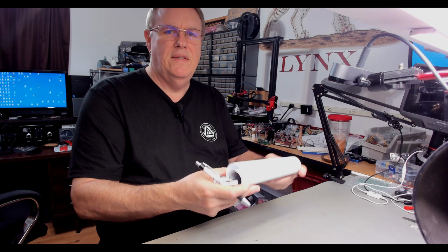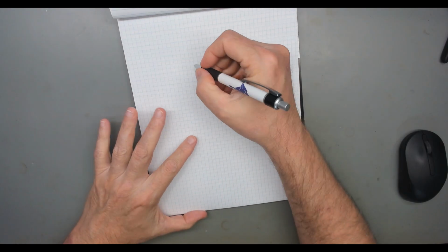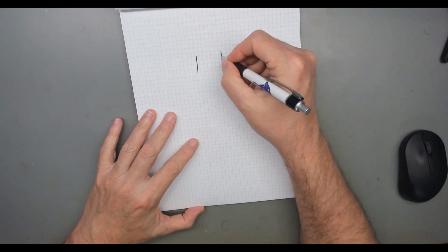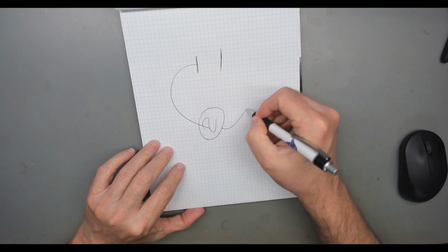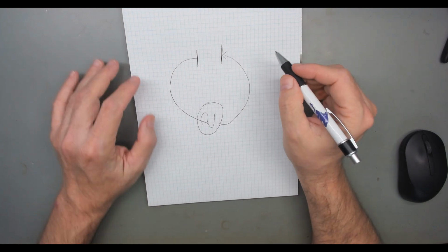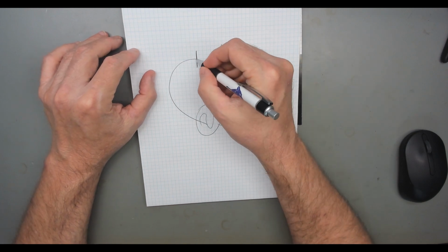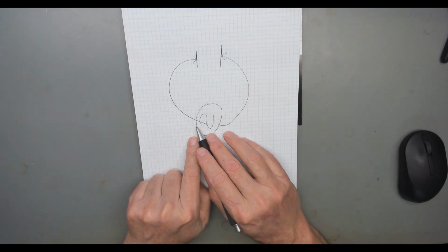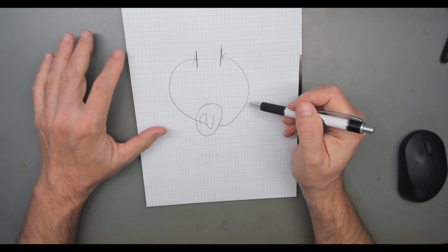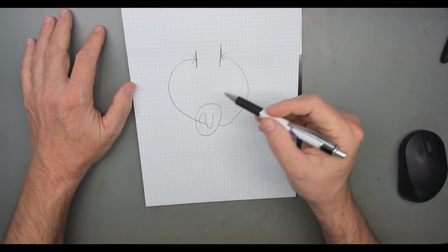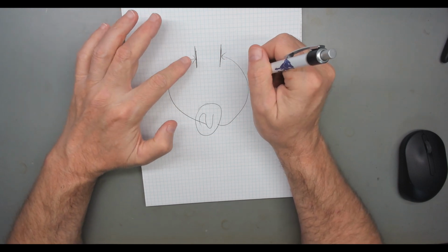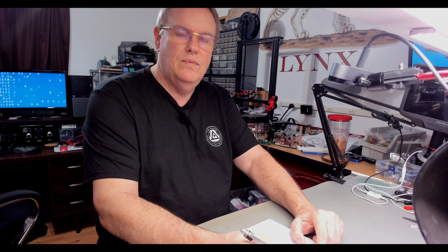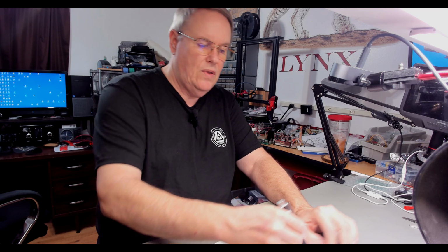Let's think of it from an AC point of view. AC is going to do the same thing. Here's our plates. We're going to put an AC source on the plate. What's going to happen is, depending on which side we are on the AC cycle, electrons are either going to be moving in this plate or moving out of this plate. It's going to be the opposite for this plate. Just as we were pulling electrons in and out of the plates, that gave us the appearance of current flow, so that it appeared current was flowing through the capacitor, but it wasn't.